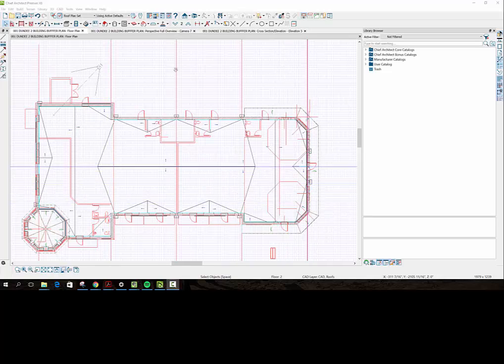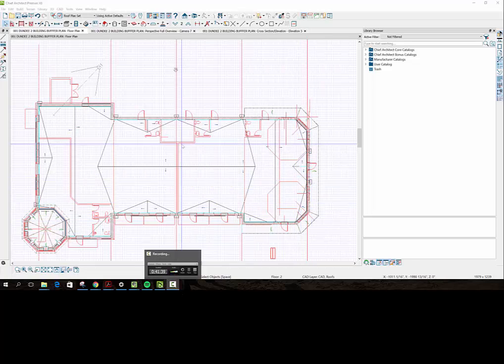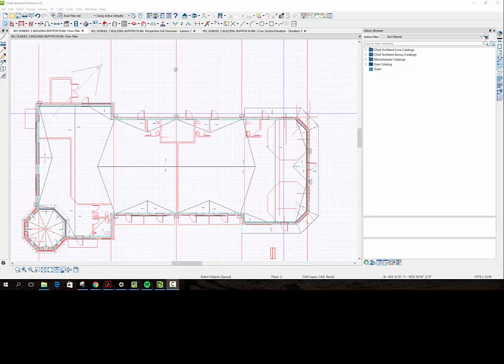And that's all we got to do. And then here this is kind of in order to drain this stuff. Water's climbing along that wall, hits here, and we really need to redirect it this way. Same thing here. Coming down, hits that corner. Instead of getting trapped, we want to redirect it to the scupper. It looks easy, but it took a little bit of sketching around to figure out how it really works.